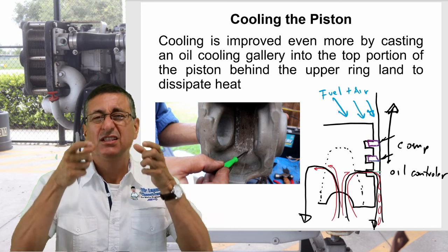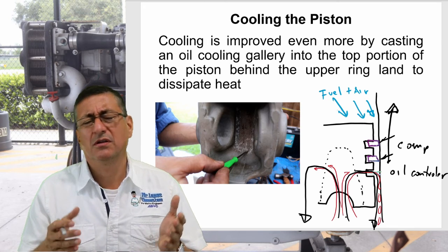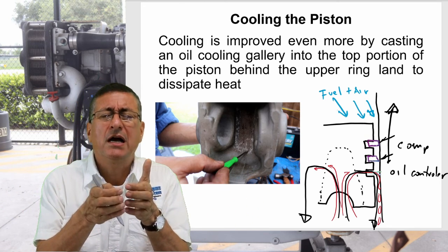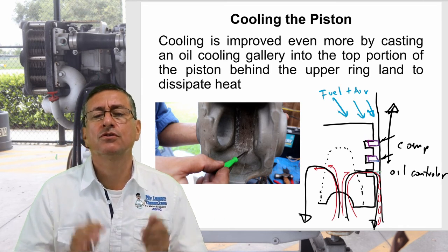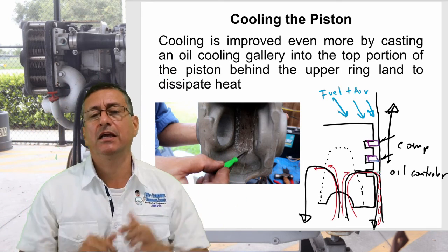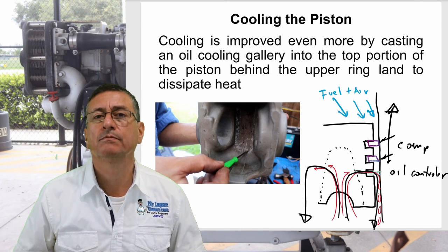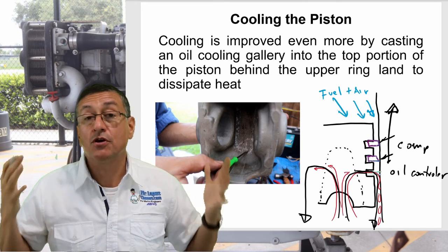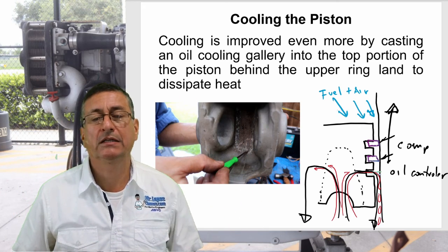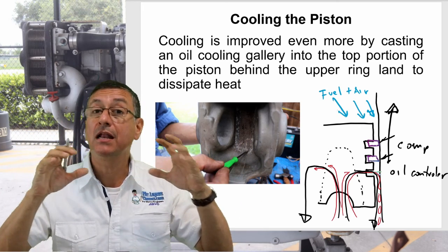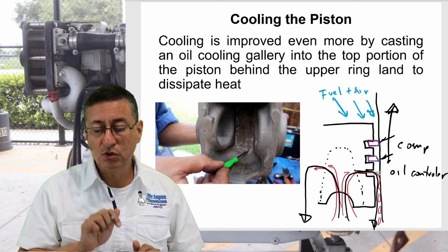The top piston rings are compression rings. Those rings seal the combustion chamber properly. Of course, if the rings are broken or if the rings are aligned, you have blow-by. But in normal conditions, the oil does not penetrate or enter the combustion chamber if the rings are in good, acceptable condition. In some specific cases the rings are broken, and of course, the oil passes. That's possible, but in general terms, no. In general terms, the oil returns to the bottom through those holes.